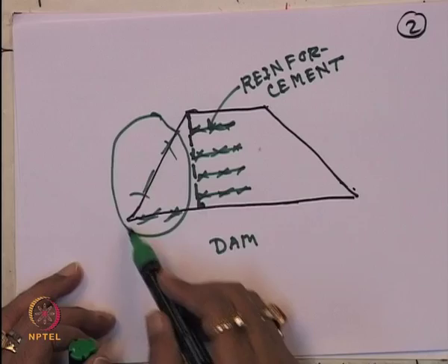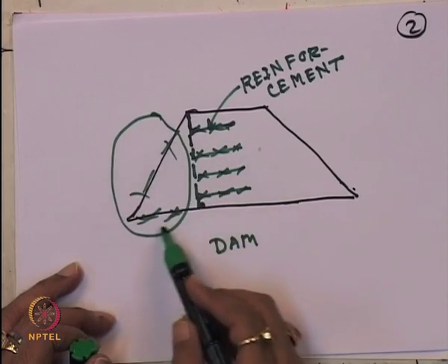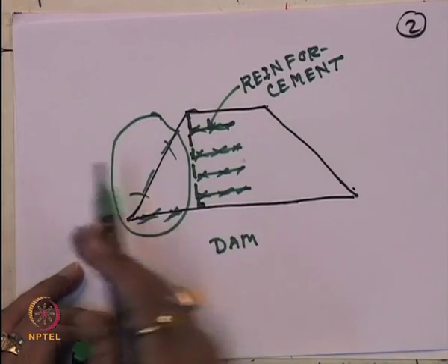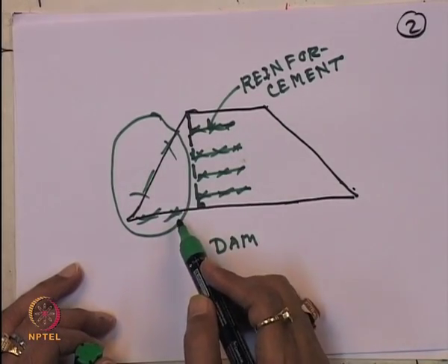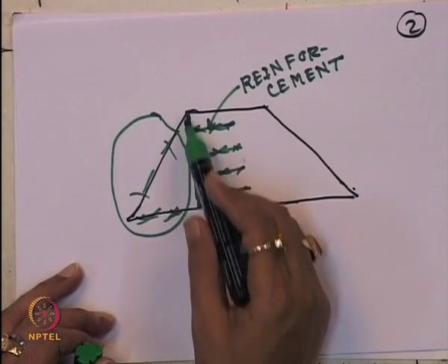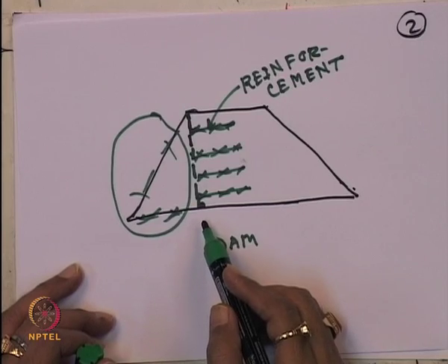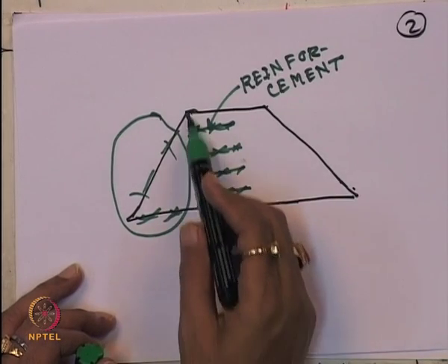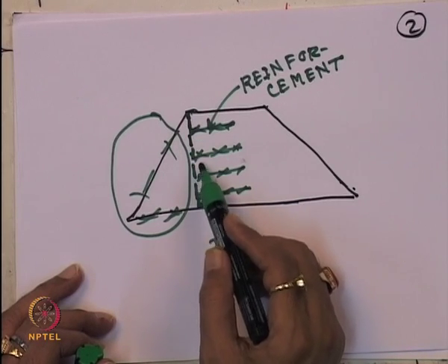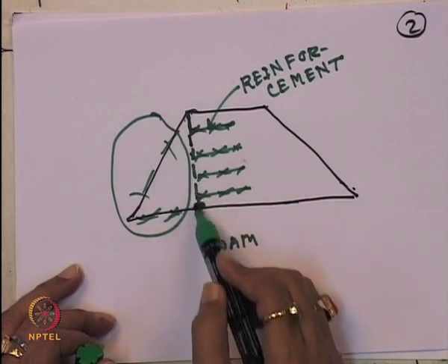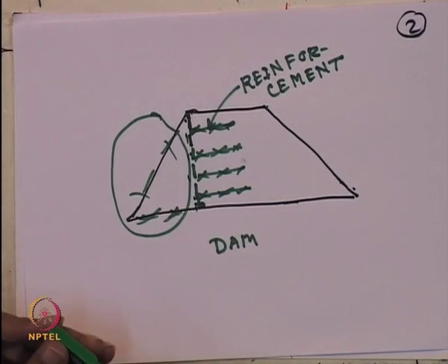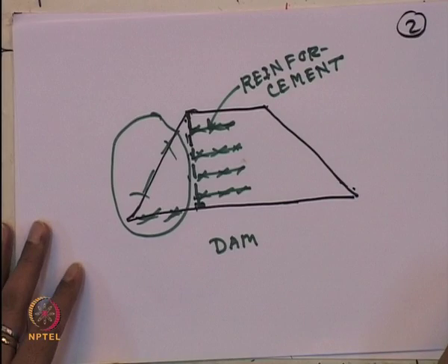You are saving a huge quantity of soil, which you would have to transport somewhere, and then compact, etc. Alternatively, you can use geogrid to make an almost 90-degree reinforced soil retaining wall, and you can provide the geomembrane in the front. So, it will be a more economical design.